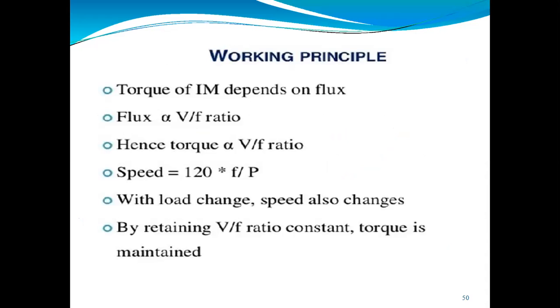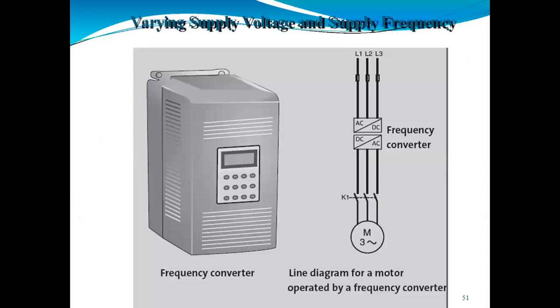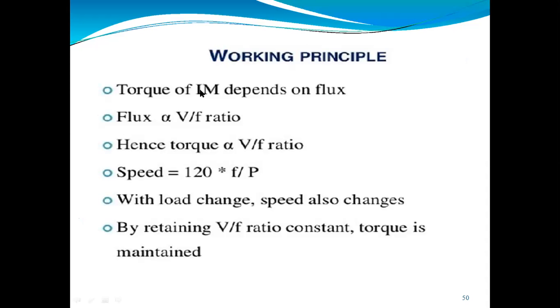When we are studying the working principle of the three-phase induction motor, IM is nothing but induction motor. We are saying the torque of the induction motor depends on the flux. If the value of voltage changes, the value of flux will change. And flux will be directly proportional to the V by F ratio, because if voltage changes then the flux value changes. So in short, we can say the value of torque will change with the V by F ratio, and you will get synchronous speed Ns equal to 120 f upon P.